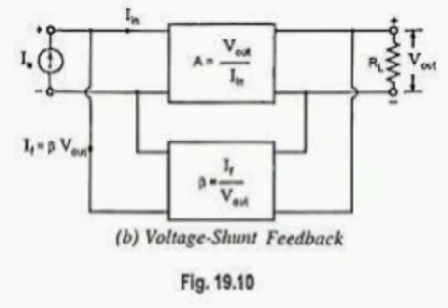For a transresistance amplifier, the output is given to beta as shunt and the input is also given as shunt. Beta has unit mho. It stabilizes the transresistance gain of the amplifier. Example: collector to base biasing.